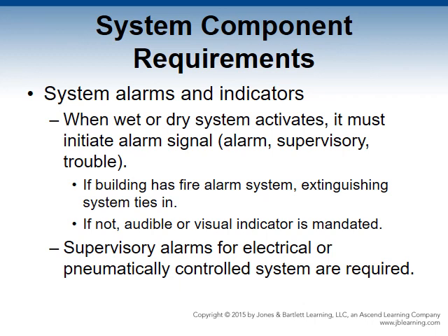Supervisory alarms are required with electrically or pneumatically controlled systems. Mechanical or electrical audible or visual indicators must be on both wet and dry systems so an individual knows the status of the system or the need to investigate.